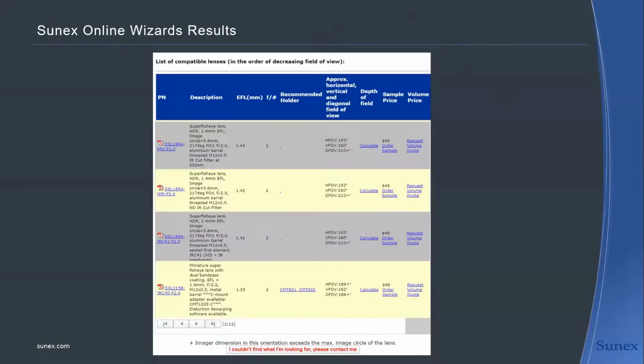So if the image circle doesn't cover the whole sensor, then you're going to get this kind of circle effect or dark corners. And even if you do cover the sensor, you still have this function of lenses that we call relative illumination. And all 3 of these things kind of play together to give you a center to edge shading effect on the sensor.